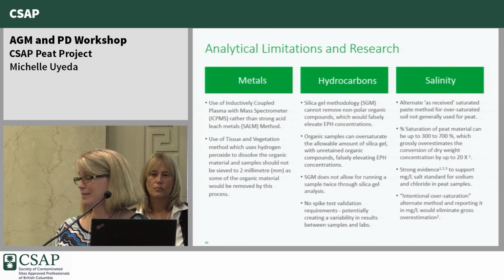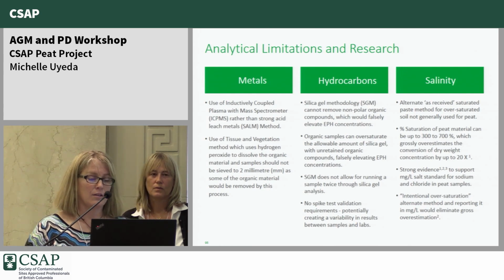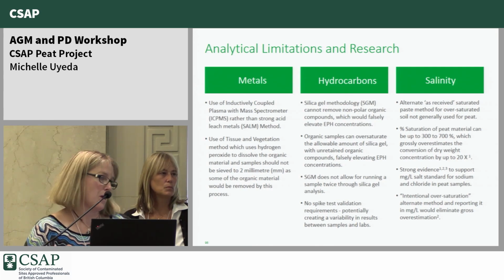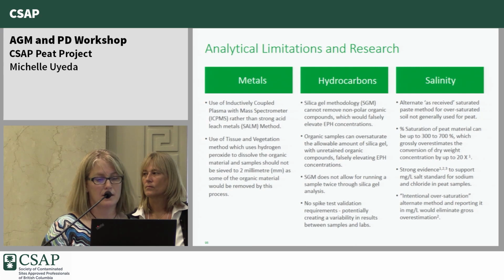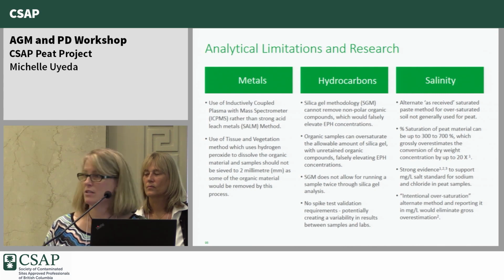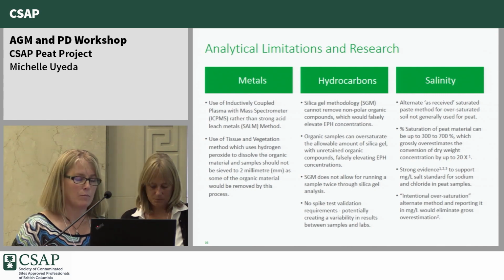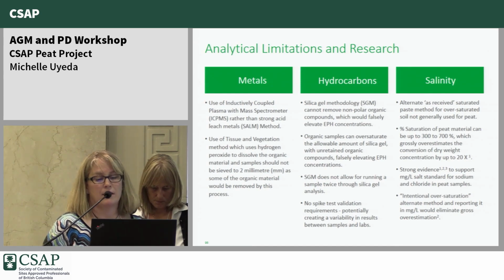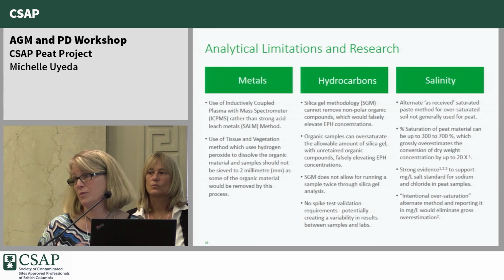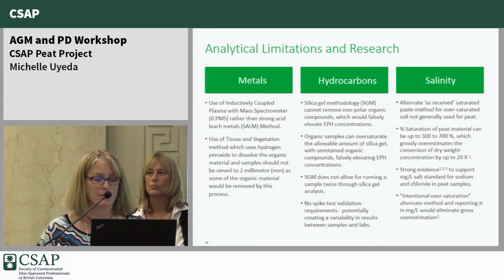With respect to salinity, I think there is strong evidence to support that for peat, because it is miscible in water, we should perhaps look at a milligram per liter unit to assess salt contamination instead of micrograms per gram, because when you do the conversion to dry weight, the concentrations can be up to 20 times greater.